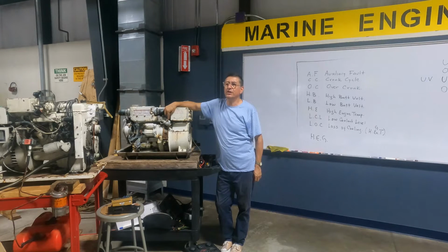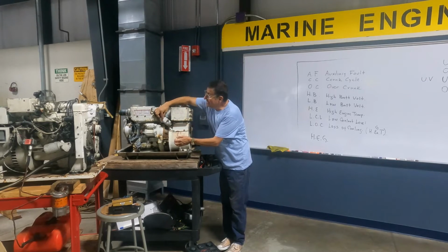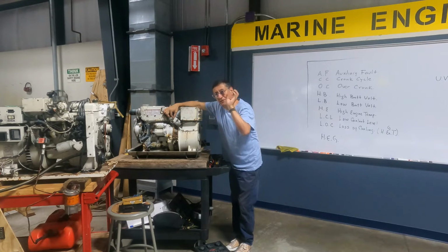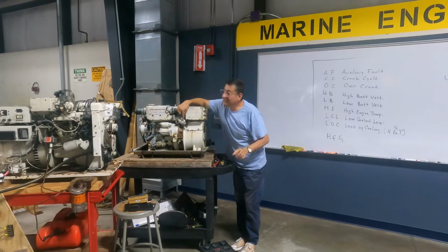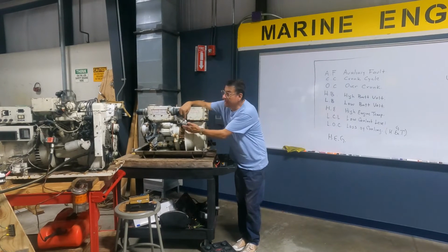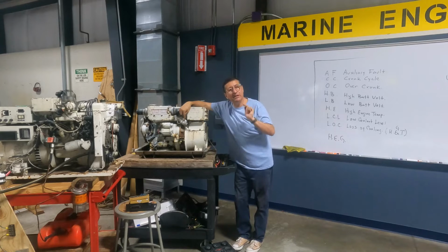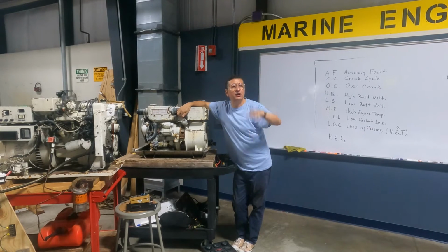Exhaust gas temperature sensor. Really it is a switch. Look at this cable, the purple cable. You remember the purple cable? The cable that supplies power for the fuel pump, for the solenoid, for everything. That purple cable passes here and continues, and this is a normally closed switch. When the temperature of this element is normal, the switch is closed. When the temperature of this metal passes the limit, what happens? It opens. And what happens with the purple cable? It's interrupted, so no fuel pump, and the engine is stopped.